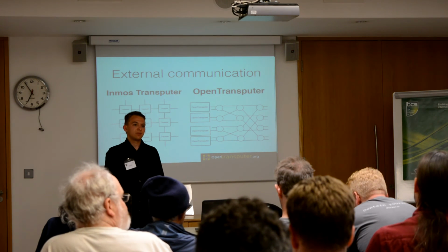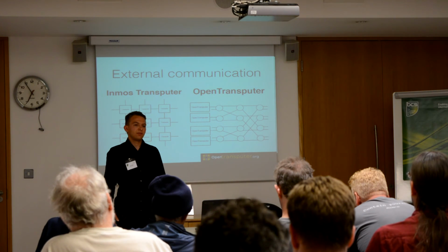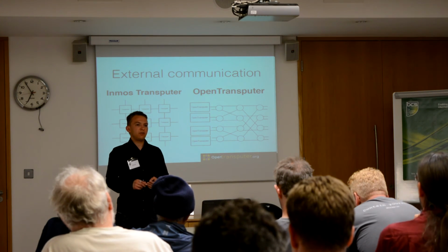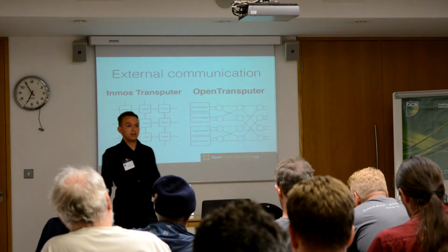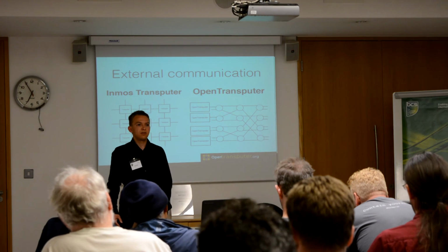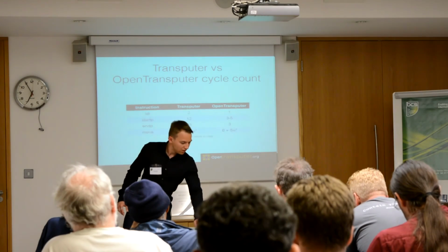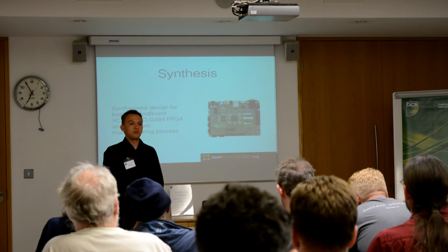Leading on from that, do you know how many LUTs and what other resources of the FPGA, what sort of utilisation are you getting for different components? Yeah, we did analyze that part quite a bit in our dissertation. I think about 35% of the FPGA is utilized by the demo that I showed in the video. So that's 35%, and it was a Set board. Yeah, that one. I'll upload the slides and we can have a chat about this later.